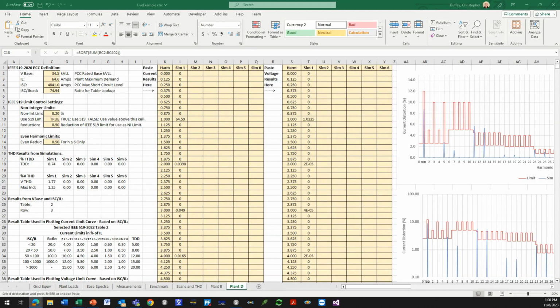It gets really messy, because the way the harmonics cancel between these source inverters is very randomish, right? If you were to go out and measure, let's say, 3 source inverters and get their harmonics and their angles exactly calculated relative to the driving voltage, which is how you have to get it. You have to get all the angles relative to a single common point of reference, which would be, for instance, phase A on your voltage. With those angles, you could get a sampling of those different source inverters and see how much variation there is in that harmonic content. You could absolutely do that.